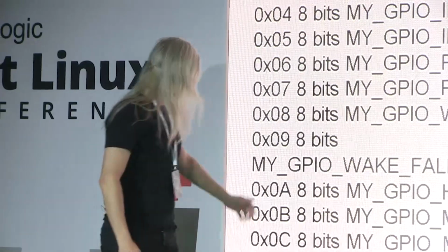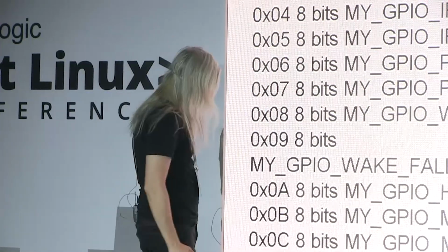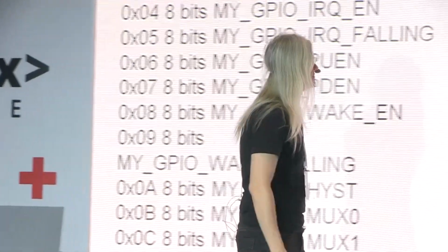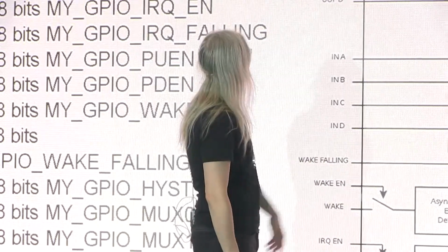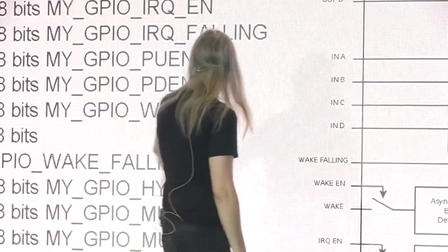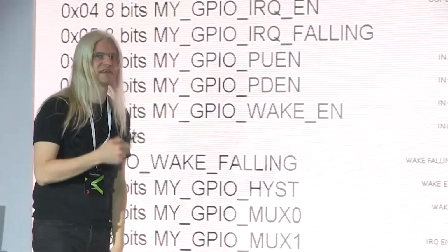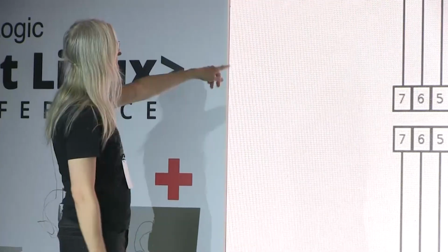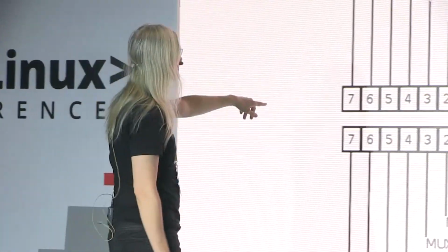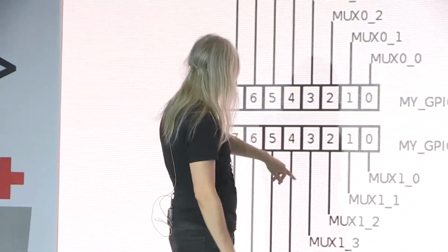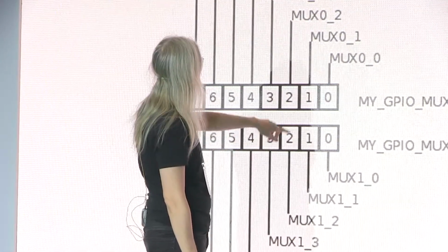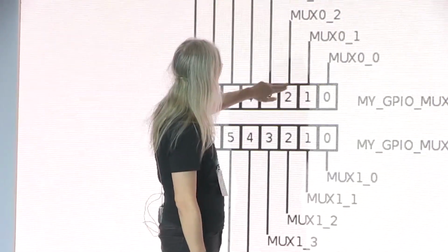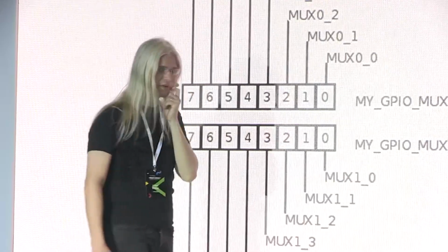We get all these registers, and since we have pin control, we have to kick in pin control and pin mux and generic pin config to handle all of the business with the lines. Those 2 things up there go into some registers. How does that register look, where you control the multiplexing? Let's see. Okay, you can put it like that. So, yeah, that's the mux line 0 from the first one, the second one, third one, and the mux 0, and so on. What's the problem with that picture?